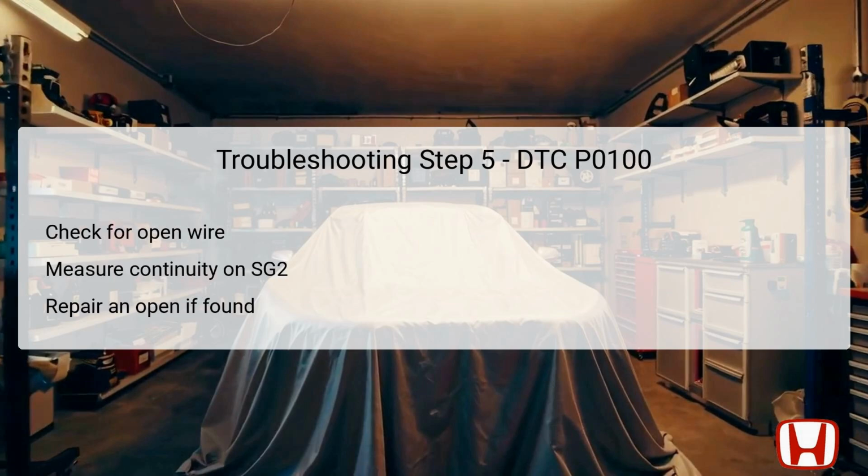The fifth step of the troubleshooting process requires checking for continuity in another wire, specifically in the SG2 line. The vehicle should still be powered off to allow safe assessment. Similar to the previous continuity checks, the focus is on determining if there is a break or open connection between terminal number 2 of the MAF sensor connector and pin number 78 of the PCM connector E. This examination will reveal if the SG2 wire is operational or if it has issues hindering its performance.